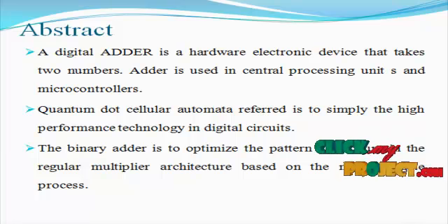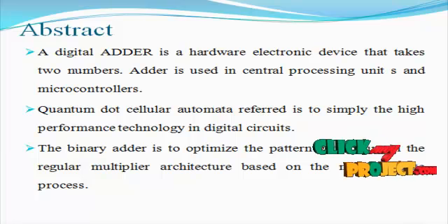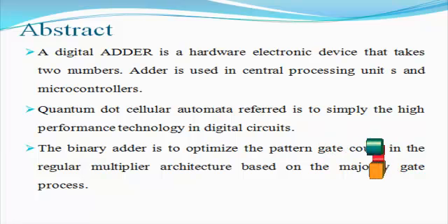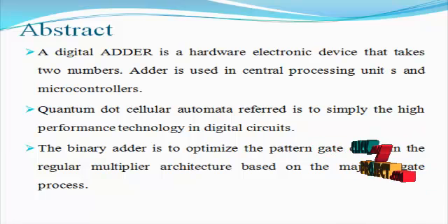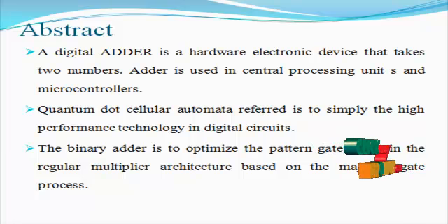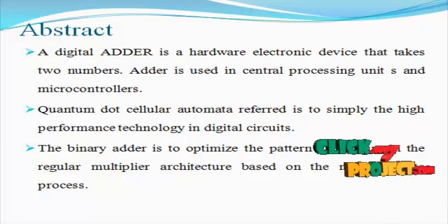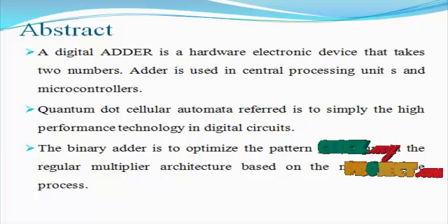Even though the multiplier is a key element for a wide range of applications, QCA implementations existing in the literature are mainly provided for comparing two single bits. Only a few examples of multipliers able to process n-bit operands with n greater than 2 are available. The multiplier described as simple computes the XNOR function, establishing whether the two inputs A and B match each other. Our work is to develop a multiplier architecture based on the QCA addition process.